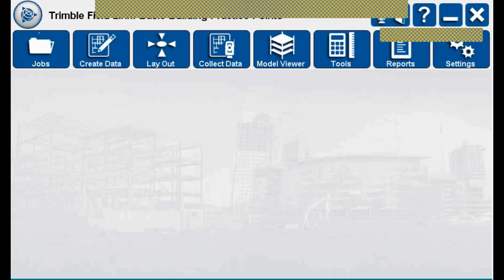So I really highly recommend making sure that that background file, and it doesn't have to be your main model that you're working in, do a save as, project-background, and then in there, set it to unitless, save, and then you can just dump that straight into the tablet. So you can try scaling it down by a 12th, but it really all depends on what that unit is set to. All right.